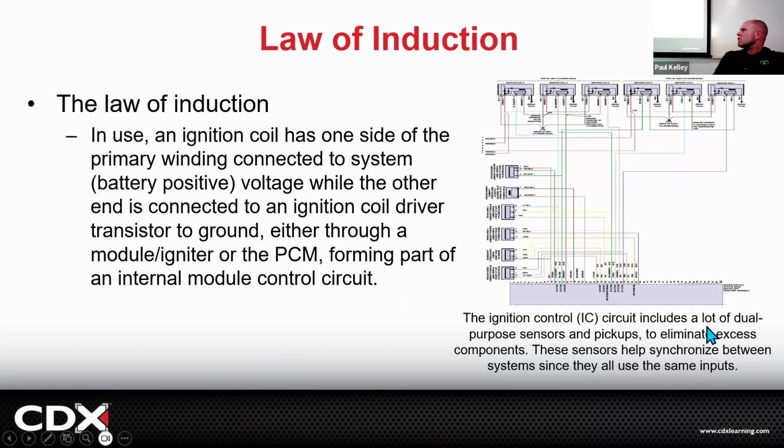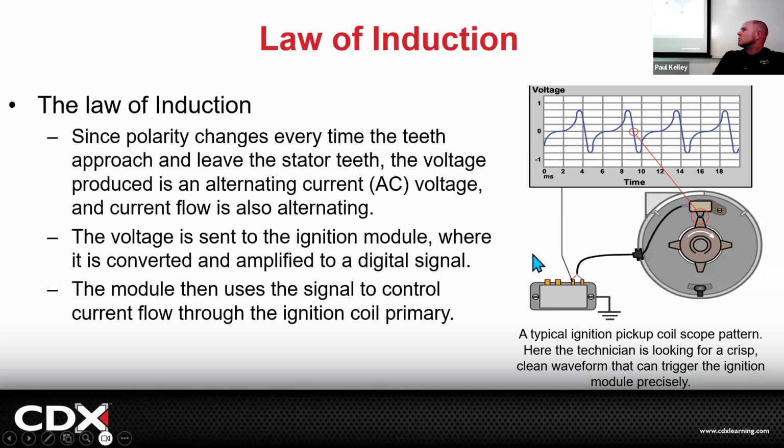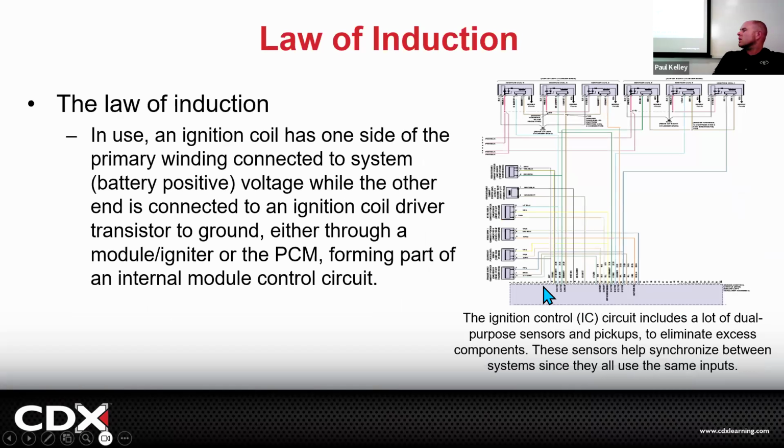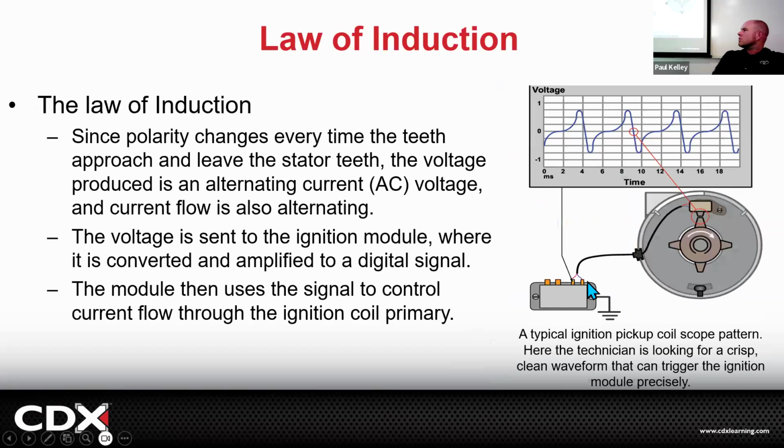The sensor will literally just be like an input to the ECM, and the ECM could actually have its own ignition control module. So if we look right here, this was a standalone ignition control module, but now for the most part, we build it into the ECM. Sometimes it's its own chip in the ECM, but you can't replace it, so it's part of it, right? So if we have a big ECM that's doing a lot of work, we're not so different than this, except this sensor was an input to just the ignition control module.